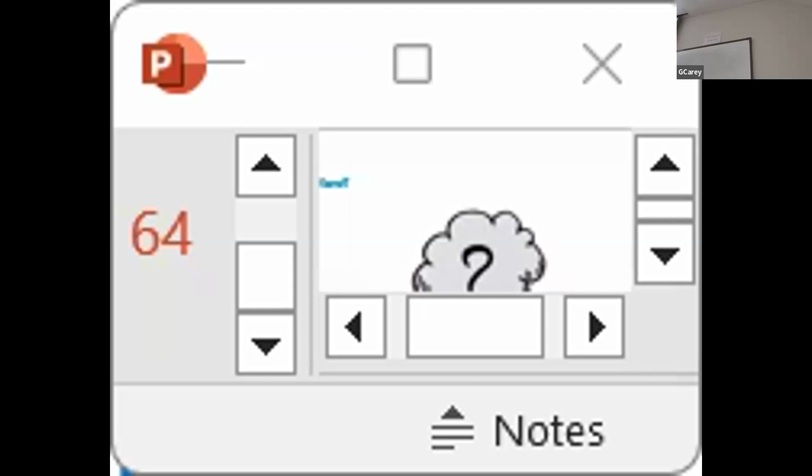Why variable speed? In that 3-ring binder of all the engineering manuals, I'm sure you've read through all of them already, one of them is about variable speed, variable volume pumping. Actually, Bell and Gossett, not that they invented it, because Mother Nature was ahead of B&G, took that fact about partial load, change the flow, change the corresponding pressure drop, and what kind of impact that can have on energy consumption, et cetera.